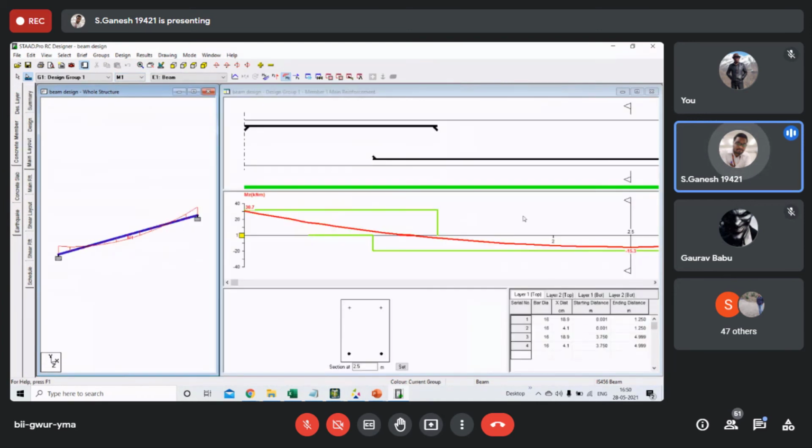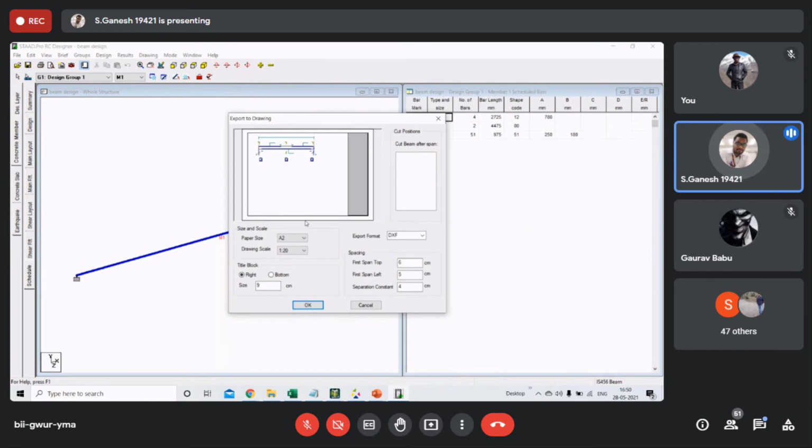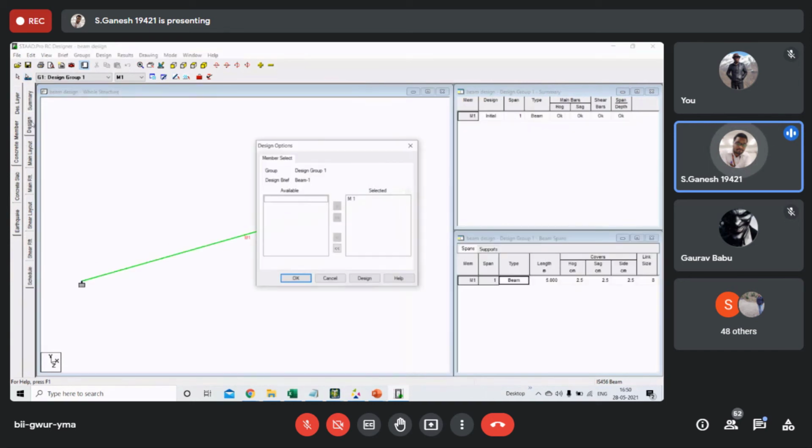Now you can see all the details, inputs, what is coming over here, where the rebars are going to cut. You can see these cut bars, and where the shear reinforcement is coming, and your schedule of bars. You can export to DXF file, the detailing of your drawings. You want to see it in A2, A4, you want to see a preview, all can be done over here. And then the most important part is this part.